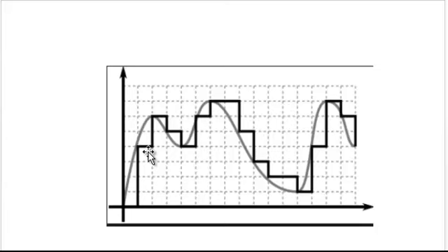Similarly here, another sample you are taking is at this instant, and this value will be given to the nearest value. And similarly this is another value you are going to take from your continuous time signal, and this value will be taken to this nearest value. And similarly here also. Like that, all your continuous values of the amplitude will be taken to the nearest amplitude values based on this discrete value of the time. So this is your quantization process.